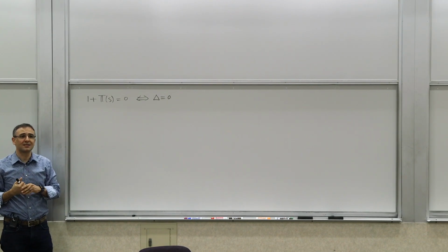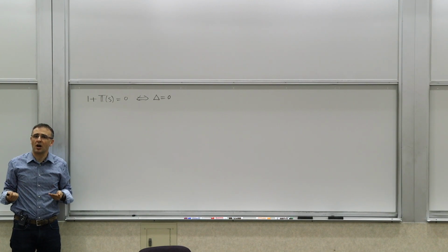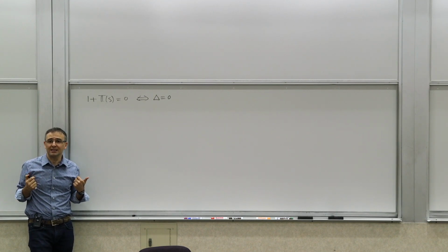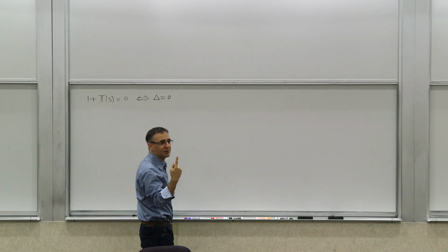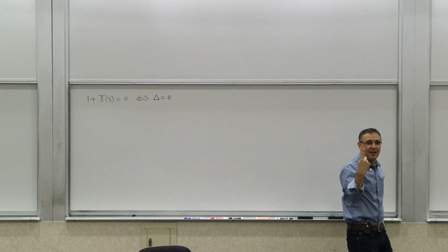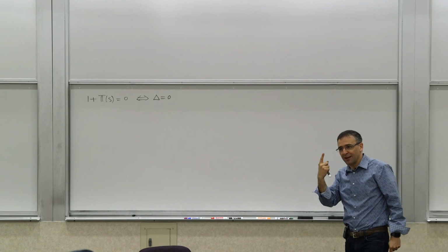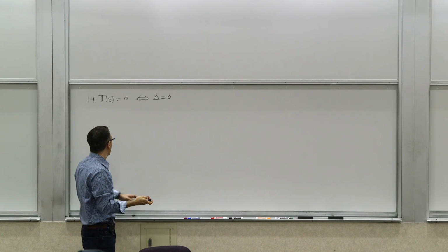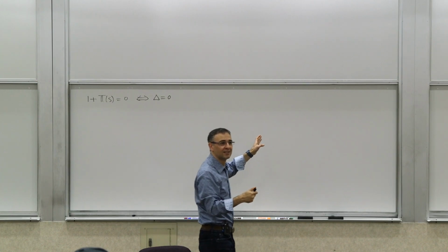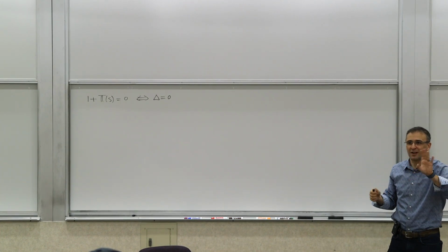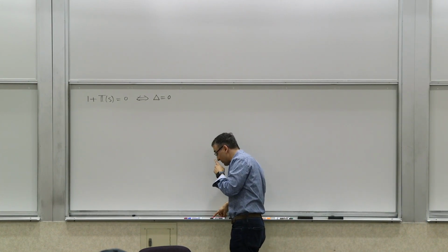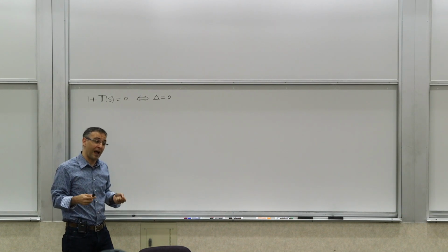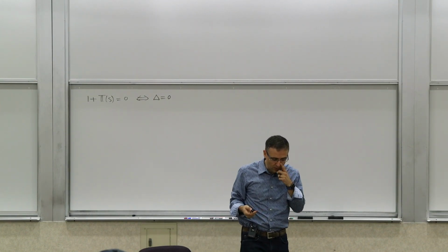To know whether or not a system is stable, we have to know whether the poles of this transfer function are in the left half plane or right half plane. It takes one crazy guy basically to destroy everything, meaning that it takes one right half plane pole to make the system unstable. It doesn't matter if you have 1,000 left half plane poles, right? Just one right half plane pole will make the system unstable. So we are trying to determine if we have right half plane poles, and the other question is how many, if we wanted to determine that.